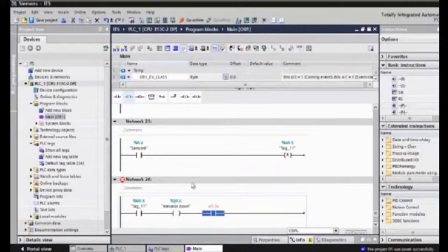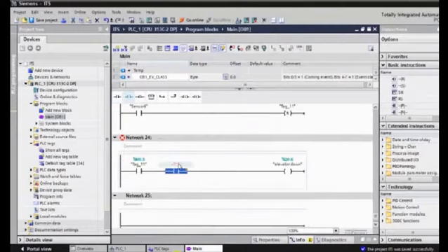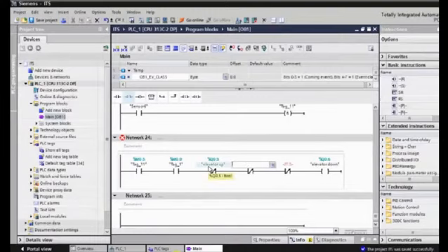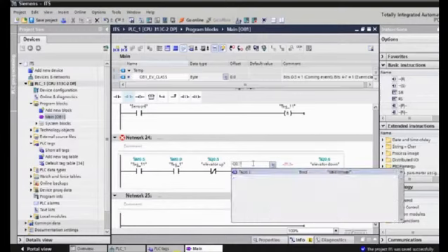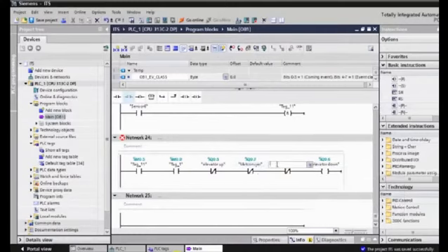We should make sure that we are already at start position M0.0 and the elevator is not going up, and the mat conveyor is not operating, and the baking is not operating.